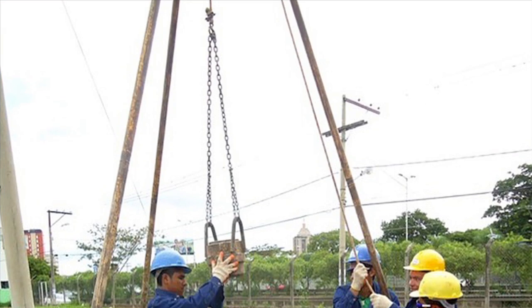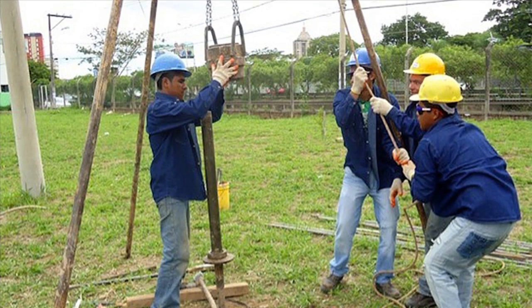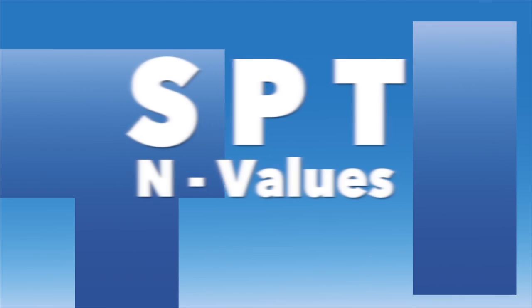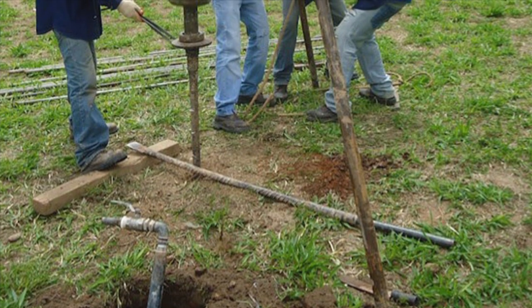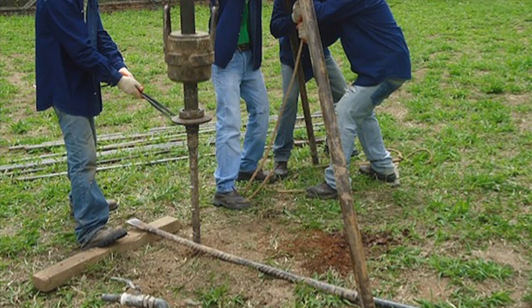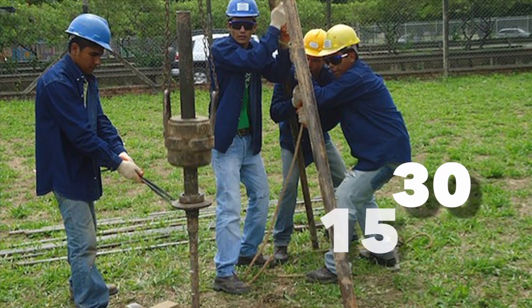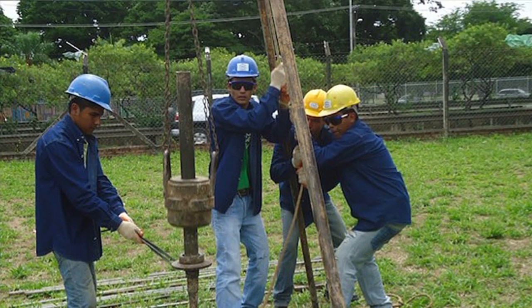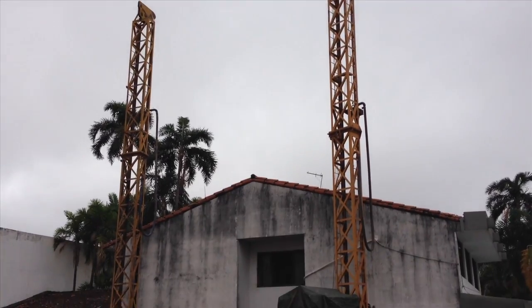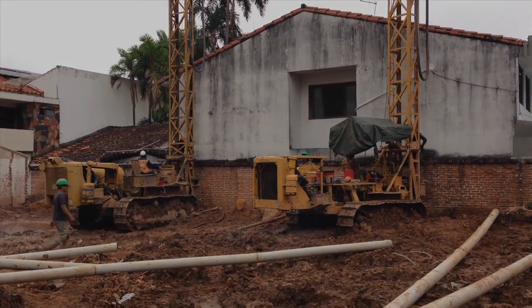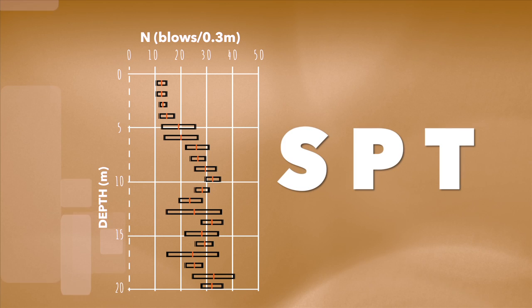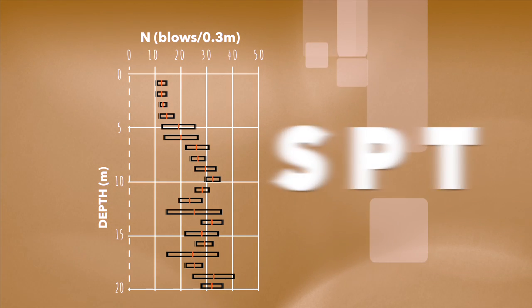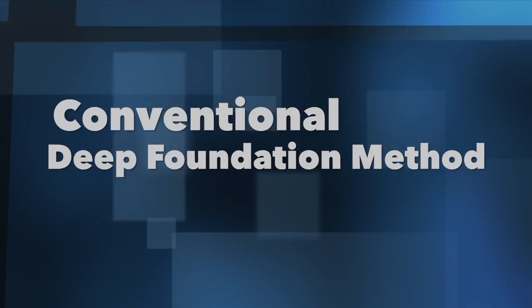The traditional soil investigation method is the standard penetration test, SPT N values increasing typically from very low values close to the ground surface, to average values of 15 to 30 at larger depth. However, the quality of SPT results is variable, as such soils are easily disturbed. The design of piles is usually based on the standard penetration test, which is performed with little or no quality control.